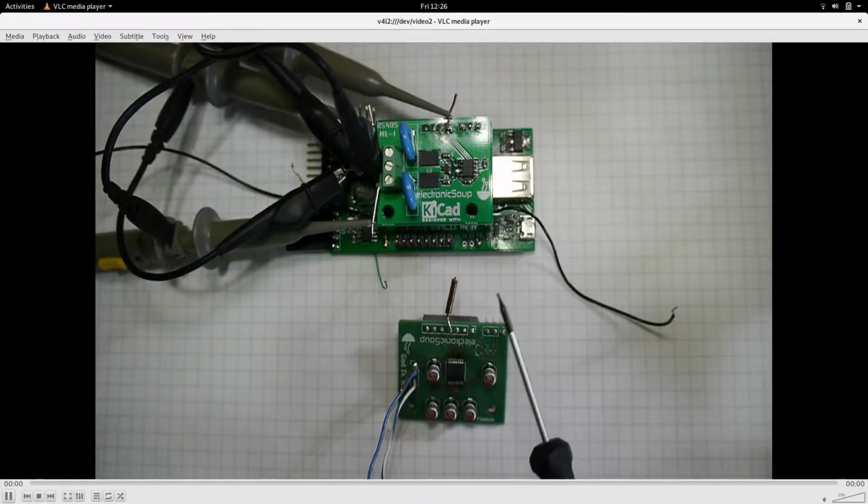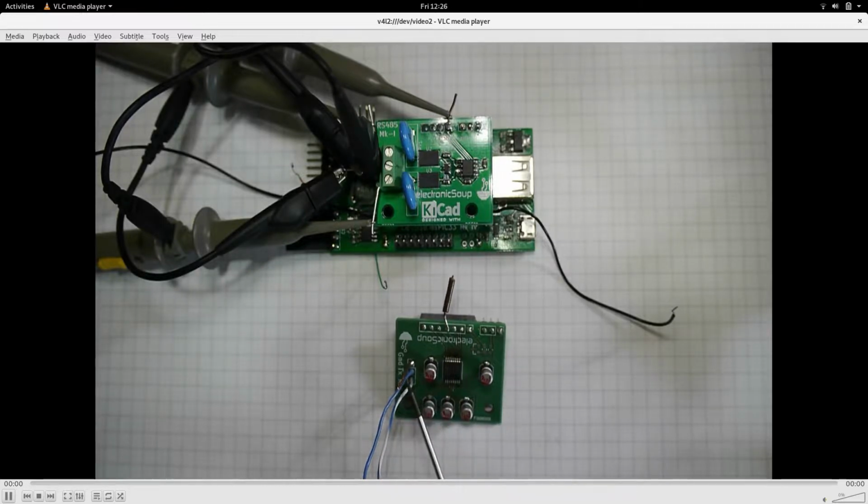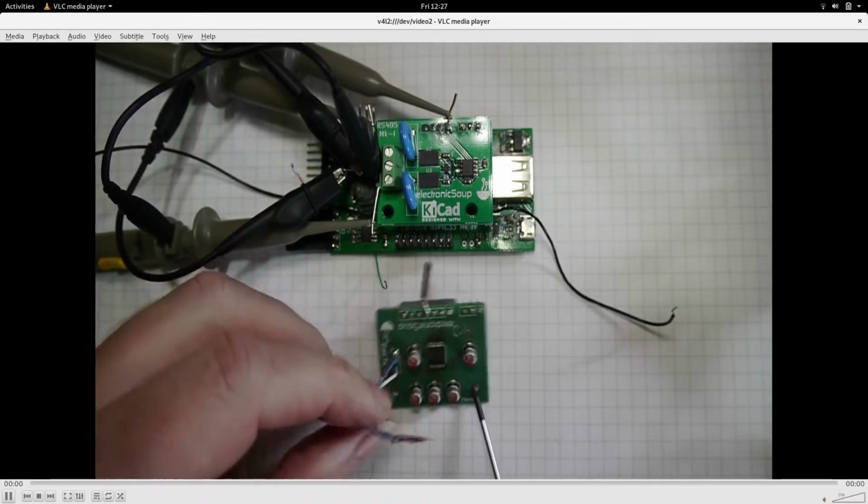So basically we've got our standard serial protocol coming in on D3 on this little board, and then the RS232 transceiver converts anything on the transmit line into a 12 volt RS232, and then anything it receives on the receive line, 12 volts, it drops down to 3v3 for our microcontroller, so that we don't blow up a microcontroller with 12 volt serial. And I looped the two wires back together, the transmit and receive, so that we could just test a loopback.